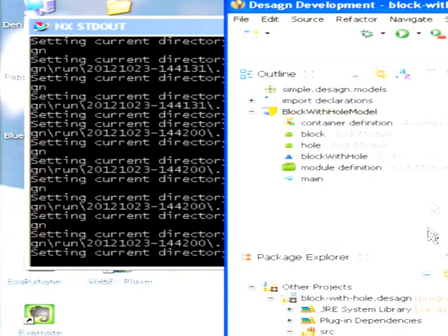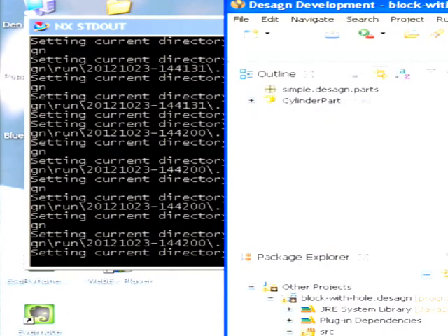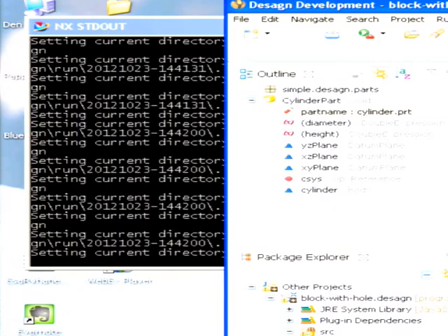For each of these CAD parts, we have a corresponding DSL construct. So the cylinder is represented by what we call a part. And this file could actually be automatically generated from the CAD part, even though at this moment we write them by hand, but they could be auto-generated. Basically, it's a declarative description of the contents of the CAD geometry. So here we have the file name of the part file, cylinder.prt.